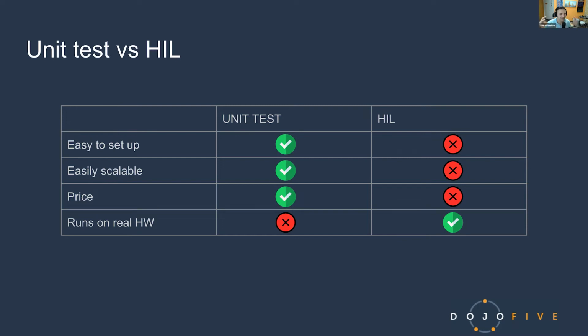So that's where I see a spectrum here: HIL on one end, where it will tell me if I've got product level, requirements level issues with the whole system, but it's not very good at telling me where the problem is. Versus unit test, where it's really good at telling me if there's an issue in individual components. But the individual components could be wired together incorrectly, or maybe the design is such that each individually looks great, but together they don't make the car drive. That's where I think there's this spectrum of focusing on what you are testing, and focusing HIL on the tests that are testing the system level behavior.